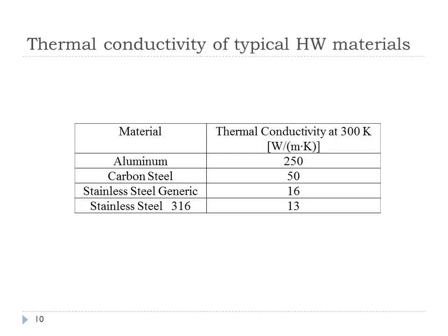So this is one of the things you have to watch out for when designing power plants. You can't just, let's say you design something for carbon steel, and it's a flue gas going to a Rankine cycle, heating up the water. If you just were to swap in a stainless steel, not only do your costs increase because of the material, but you also have to look at the fact that your heat transfer coefficient has likely dropped significantly, and that could have a negative effect on the overall power plant.